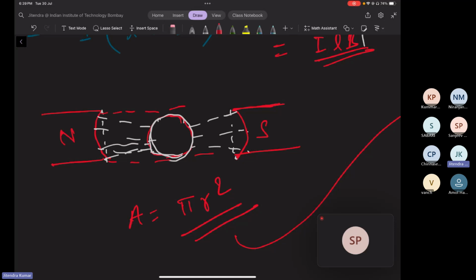So we want to fully utilize our permanent magnets. As you know, permanent magnets are the costliest component in these instruments. So that is why we go with the electrodynamometer. Further on we will see that in the electrodynamometer, in place of permanent magnets, we have a coil which is used to produce the magnetic field, so electromagnets basically. The same amount of flux will be produced by a coil wrapped on a core. So the coil will produce the field and we can avoid permanent magnets. Okay, I hope I am clear.